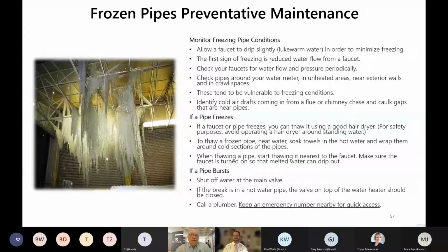And I think that's probably enough of the pointers off of this. I believe, Ken, you've circulated this to some of your folks. So yeah, I'll circulate it back out again, just as a reminder. The reason we're mostly concerned about it, and Maya's on the call as well and they're concerned about it, is a lot of folks have put their systems in bypass or mechanically forced open that we haven't had to do historically. So what we're seeing is that's opening a potential risk: the system's in bypass, we're bringing in more air, but our building doesn't have glycol in the heating system. So are we going to start popping coils? Yeah, it's just making everyone aware that we're vulnerable.